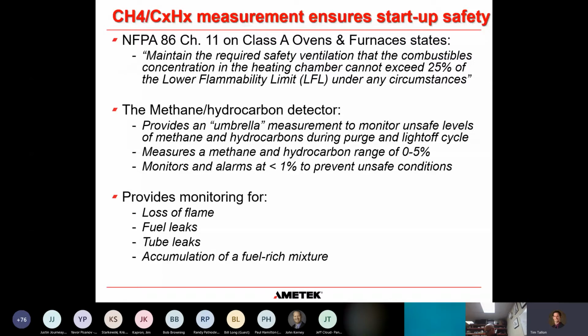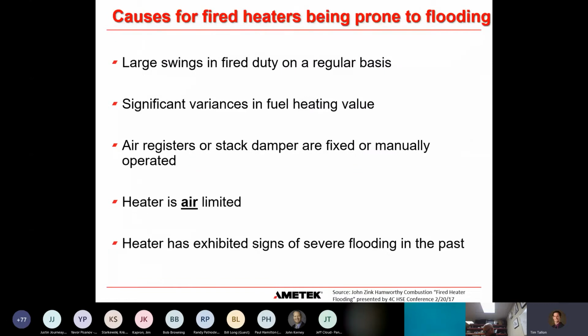But what we've found is that the methane detector has also provided a means for monitoring for other unsafe conditions in operation, not just startup. Those would be things like loss of flame, fuel leaks, tube leaks, and also any type of accumulation above fuel-rich mixture. So let's talk about that for a second.